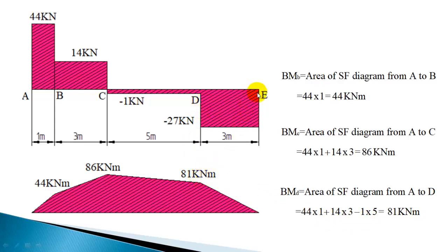And the bending moment at D is going to be 0 if no couple is acting. Directly you can get 0. Or if you calculate the total area from left hand to this, you should get 0. You can do this from the right hand also. At D, the bending moment is this area.